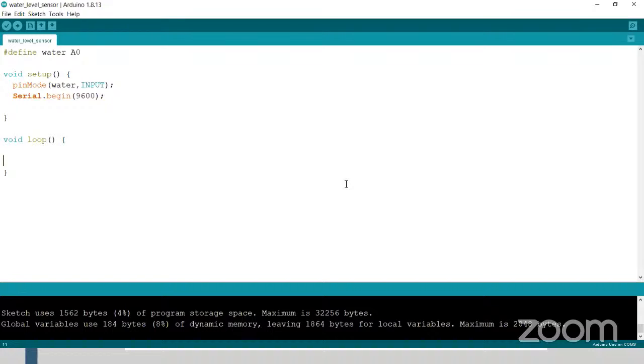Then I am using Serial.begin. Serial.begin is also one instruction. Definitely, S is capital, and before using begin we definitely give one dot. This will be acceptable for the Arduino IDE software. This is one instruction; you fix the baud rate via this command only. Okay, then